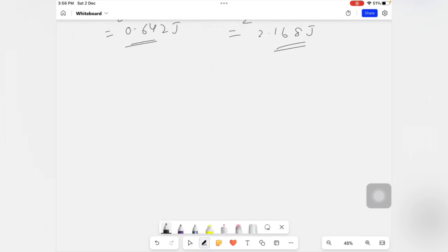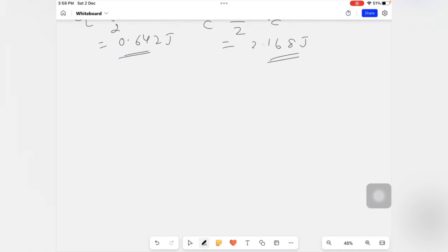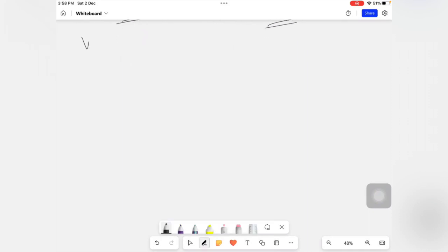Next, very important is draw the phasor diagram. As we know here, in the given circuit, because XC is greater than XL, it acts as a leading circuit. It acts as an RC circuit. Current is leading. Now I will draw the vector diagram.